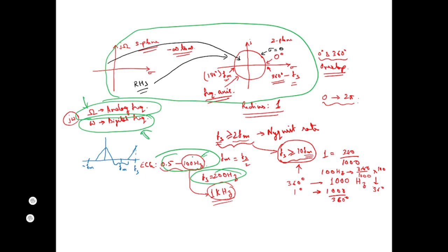Most laboratories, especially in India, have low cost data acquisition systems, so you have to be very careful. Whatever your maximum frequency FM is, you should take a sampling frequency which is at least 10 times your maximum.